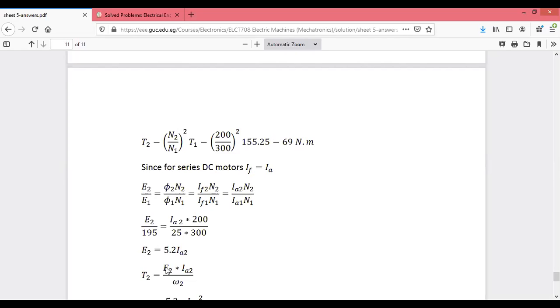But when solving the equations for torque, we have torque equal to E IA over omega, or the equation P equal to T omega, torque into angular velocity. If you equate these equations, we already saw them in the torque equations, so we can take torque times omega equal to E IA. So I am rearranging those equations to derive the value for torque T2.